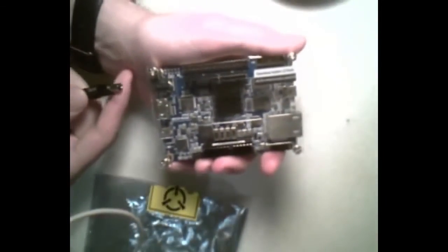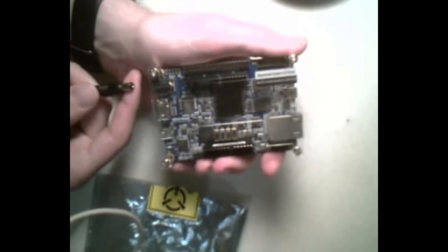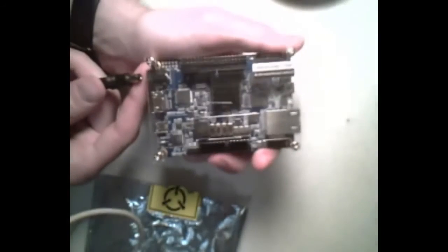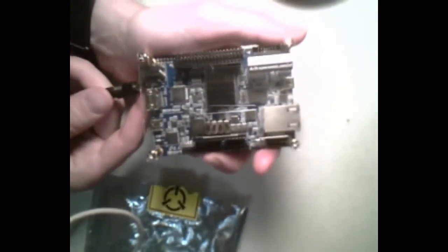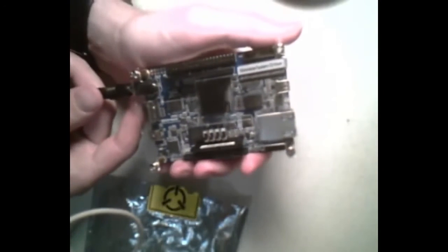I'm going to take the power cable. Make sure your micro SD card is removed. If you leave that in, right here, so the board is oriented like this, and if you turn it this way, there's the micro SD card slot. If you leave that in there, it's going to erase whatever design you try to program to your board. So I'll leave it on there for like 2 seconds, and then a watchdog timer goes off and erases your board. So remove that SD card so that it's not there. If you can't get this to work, just look closely at the My First FPGA from start to finish. That shows you the whole process of getting this thing programmed. Okay, supply power.